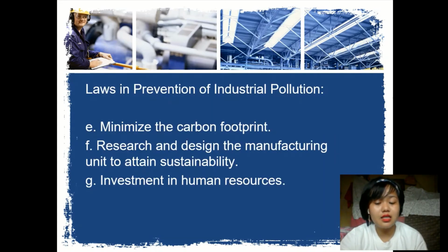The fifth law is to minimize the carbon footprint. Carbon footprint is the amount of carbon dioxide and other carbon components emitted due to the consumption of fossil fuels by a particular person or a group. Components that are responsible for a high carbon footprint during construction are over-designing and the use of large quantities of cement and metal. Components that are responsible for a high carbon footprint during operation are electromechanical devices such as pumps, scrapers, aerators, and heaters.